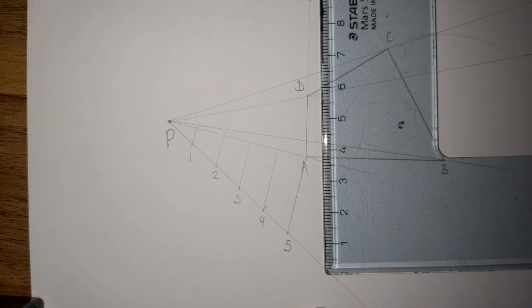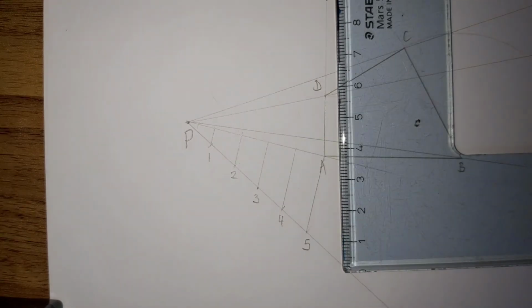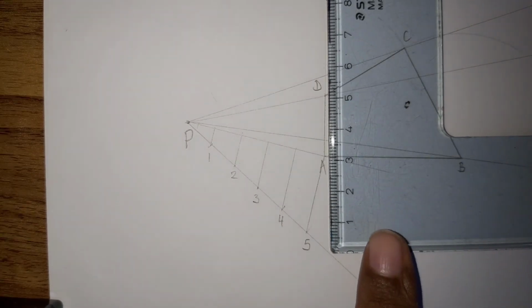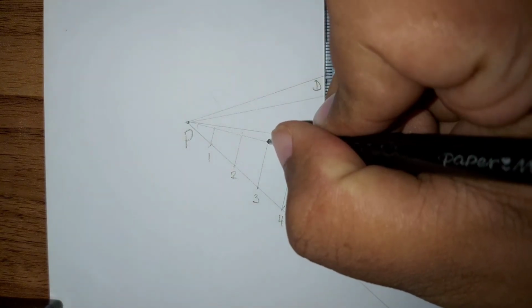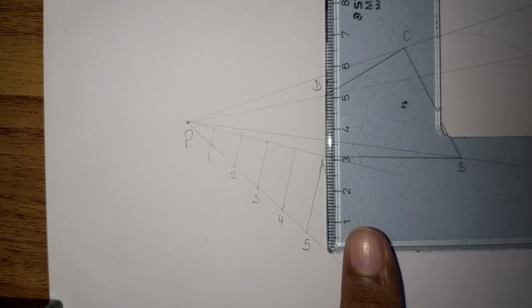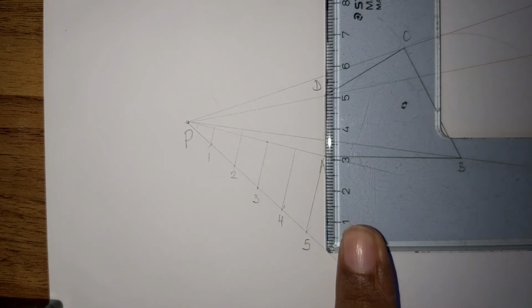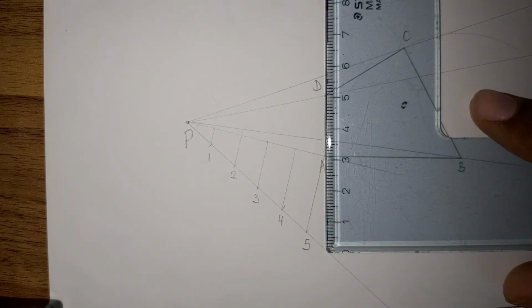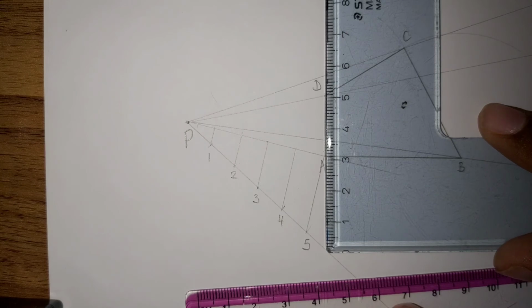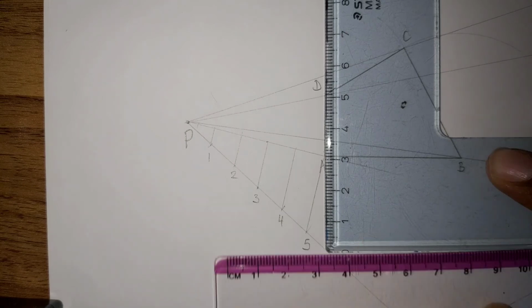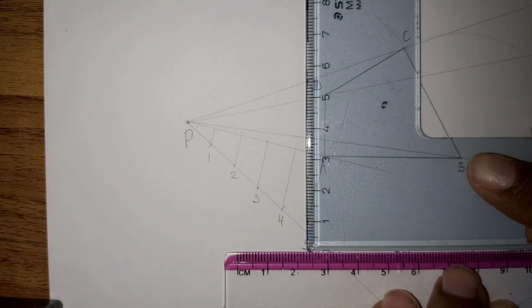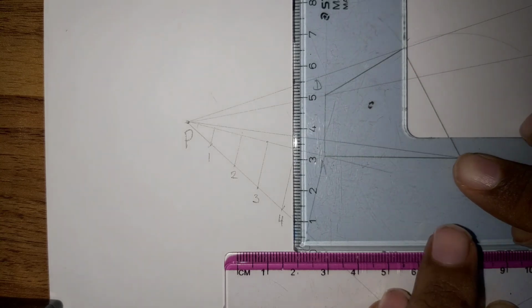So now the next step would be to set your set square parallel to DA first. And you can see me marking off where the third division is, since the first number in the ratio is 3. Remember the ratio is 3 to 5. We're going to slide that line to where number 3 is, or to where the third division is.